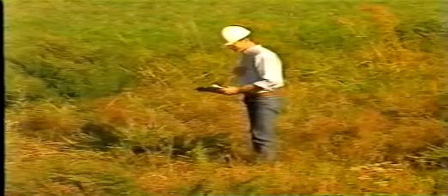Keep in mind that while shallow-rooted vegetation offers erosion protection, too much vegetation obscures the surface of the dam and hides potentially serious deficiencies. And deep-rooted vegetation can provide pathways for seepage. Animal burrows can also provide pathways for seepage. Heavy infestation on small embankments is of real concern.